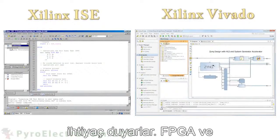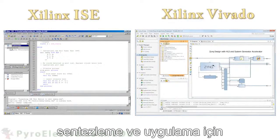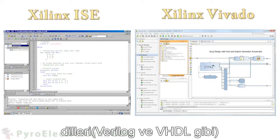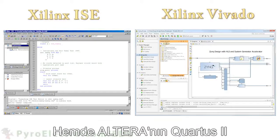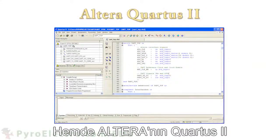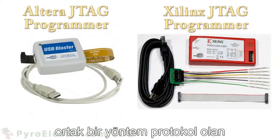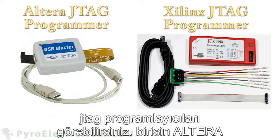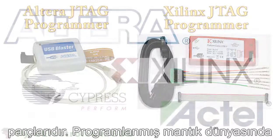To build up the FPGA or CPLD images, most companies will have their own software for synthesizing and implementing. Hardware description languages like VHDL and Verilog are used in these programs, like Xilinx's ISE and Vivado, as well as Altera's Quartus 2 program. A common method for loading images onto CPLDs and FPGAs is through a protocol called JTAG. Here you can see two JTAG programmers, one for talking with Altera parts and another for talking with Xilinx parts.